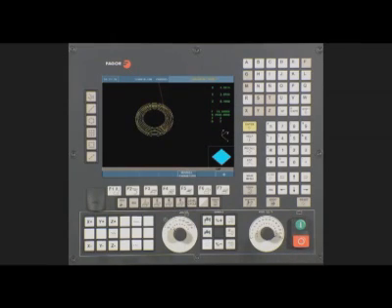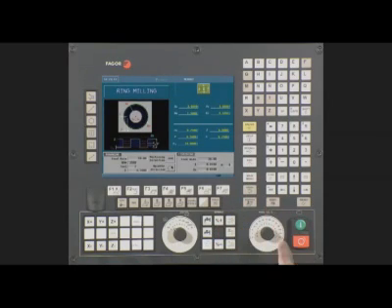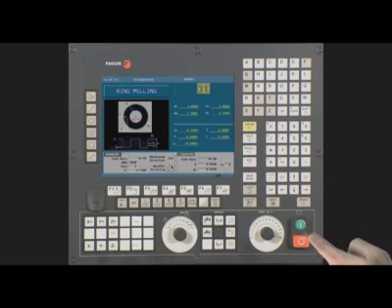Confirm that the cycle has finished with no errors and you are now ready to save or execute the cycle. Note, if the graphics are too small, press Display Area and select Optimum Area. The CNC will then automatically adjust for best graphic view. To execute the cycle, press Escape twice. You now see that there is a Cycle Start icon at the top of the screen. Turn down the feed rate to 0 and press Cycle Start button to begin executing the cycle.